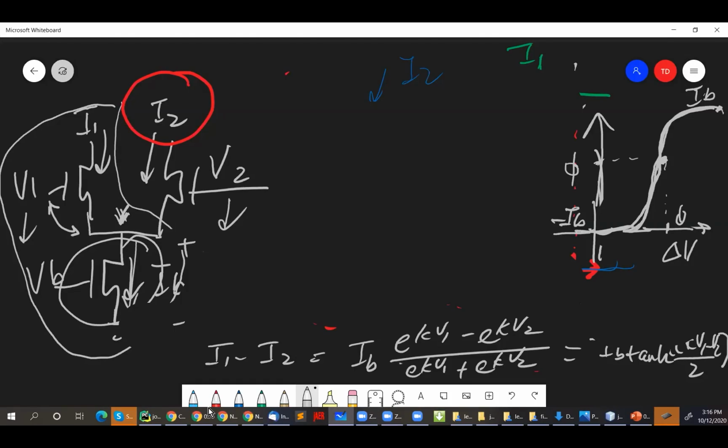It's very dependent on the VGS of the transistor, right? Both V1 and V2 have a VGS that's a function of the little v. For first order analysis, it's true that one of them could go into subthreshold, but I think it's too painful to do this. So the easiest thing is to say the bottom transistor is running above threshold, I assume it's in saturation, even though it might not be.